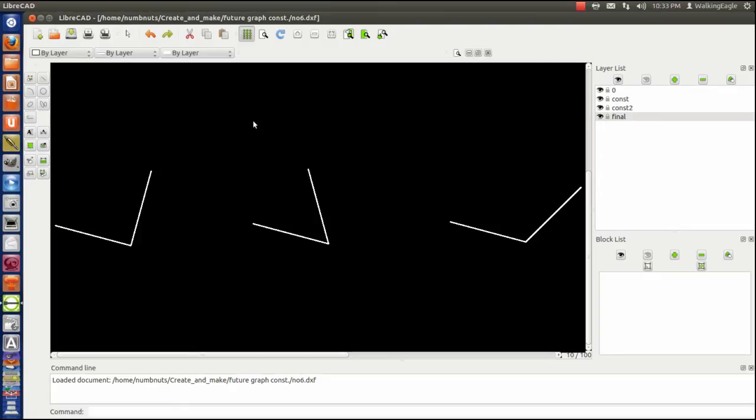Usually when you're doing this, what you're wanting to do is round off the corners. And built right into LibreCAD is a function called round. And it does that. And what I've drawn on all these lines, this one's a 90-degree angle, but I've got it rotated 15 degrees from horizontal. This one's a 60-degree angle. Also, the bottom's rotated by 30 degrees. And then, by 15 degrees. And this one's also, the bottom's rotated by 15, but it's a 120-degree angle. So 90, less than 90, greater than 90 is what we're showing here.